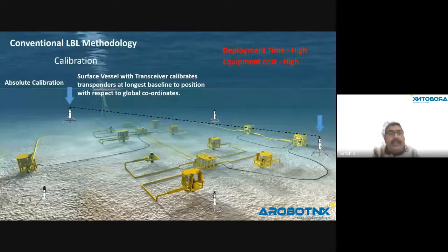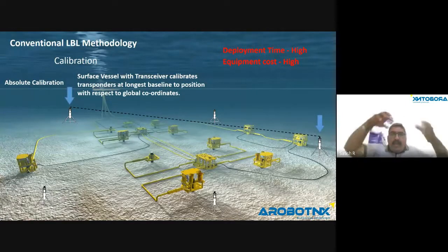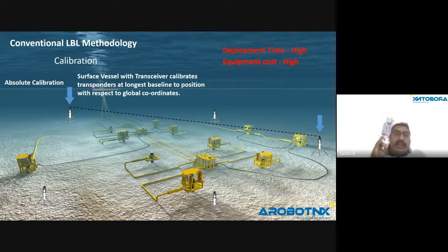There are two things you have to carry out in an observed calibration. First, the observed calibration happens like a boxing. Boxing means you spin around. It's a traditional USBL calibration method. You spin around a beacon and carry out at 40 to 100% of its depth. You just have to make a diameter and spin around. What we are going to understand from that is the error in the multipath, that is, if there is any rebounding on the beacon, because the beacon is fixed and you are rotating. The second important thing is the sound velocity range error.